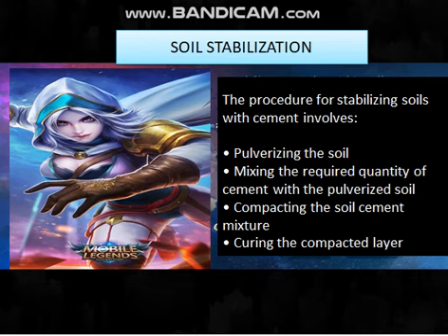The last one is curing the compacted layer. The moisture in the compacted layer must be prevented from being lost before setting is completed because the moisture is required for the hydration process. This is achieved by applying a thin layer of bituminous materials. So that is the procedure for stabilizing soil